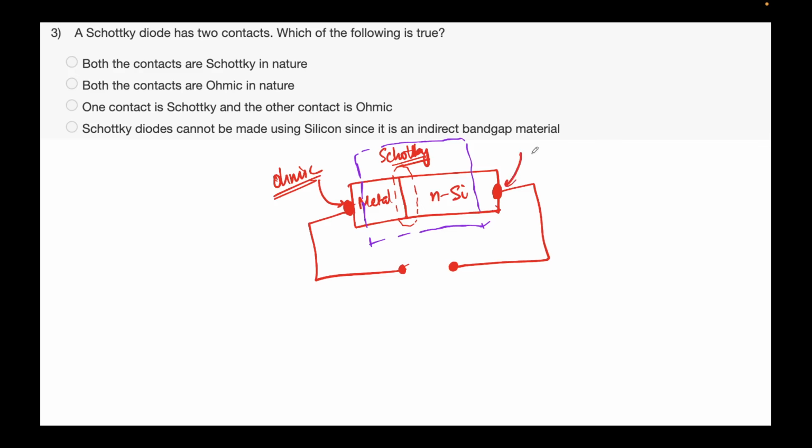So what I want is that I also make this contact an ohmic contact. If you look at this whole device, here it's a metal contact. Again, this wire I'm assuming to be metallic. So we have an ohmic contact on this side, and I want to analyze the Schottky diode. The Schottky barrier or the junction that I'm forming, I will form it as a rectifying one. Otherwise, if I don't make this rectifying, then this will be metallic, so essentially I made a resistor. So I want to analyze this, and I'm assuming this is a rectifying contact that I'm making.